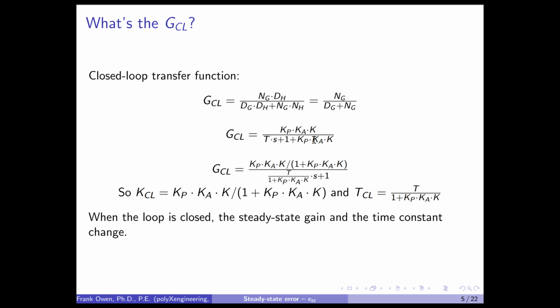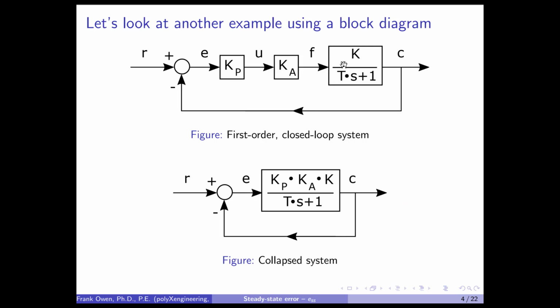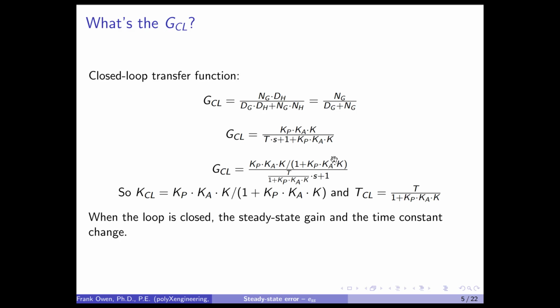Now, this is a first order system. It has an S to the first power in the denominator, and that makes it a first order system. But normally when you have a first order system, you want it in the standard format for a first order. What characterizes it is that the non-S term has a 1 there. It's not anything but 1. Now, if we look at the non-S term in our formula, we have a 1 there, but we also have this. This is not any part of S.